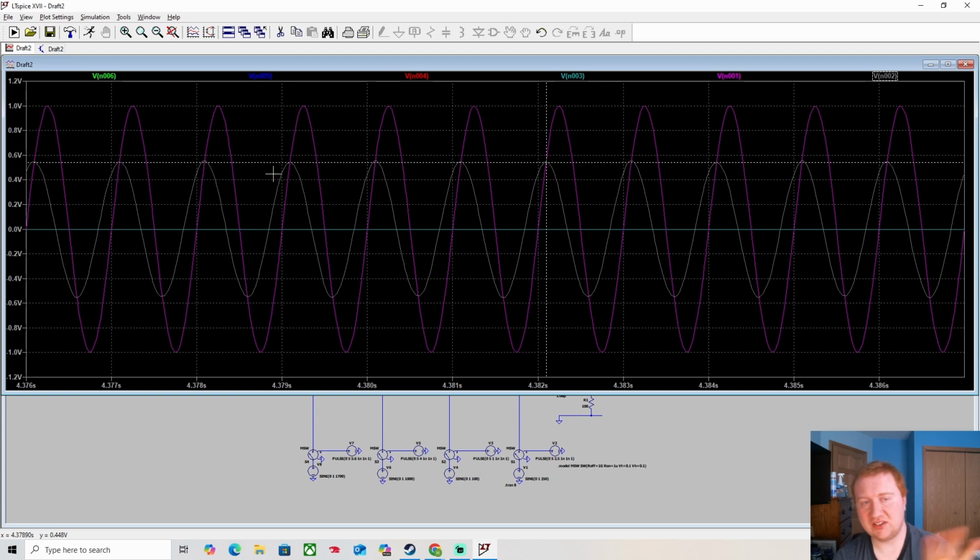And this is the phase shift effect. You're actually seeing that the output no longer lines up with the sine wave, because the capacitor is making it lag behind the initial frequency. That's the nature of filters, capacitors and inductors. I believe an inductor would lead it, so the sine wave of the output would be ahead of the input frequency.